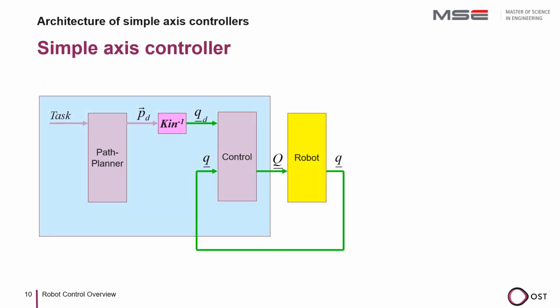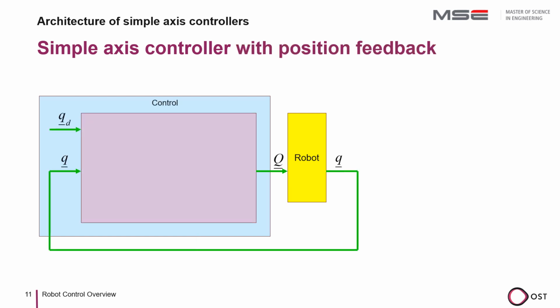Let's take a closer look at the internal structure of the previously presented position controller. The controller requires the difference between the set point position and the actual position in order to calculate its correction force. We refer to this controller error here as e. But since it is a second-order system, the controller could oscillate undamped, which is why we also need the derivative of this error, which we denote here as e dot. This derivative is identical with the velocity error.